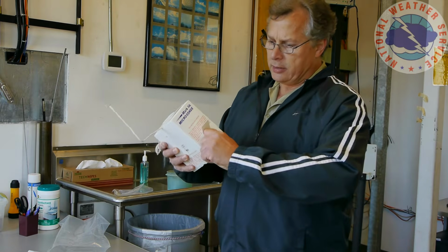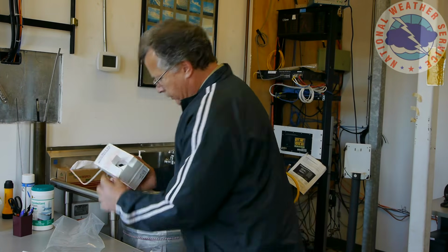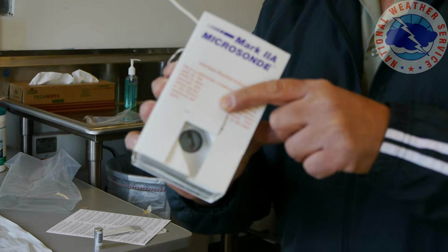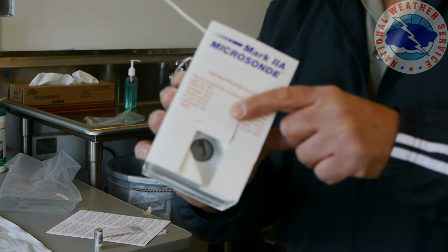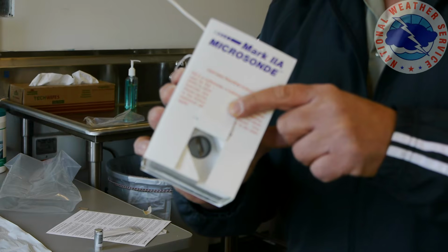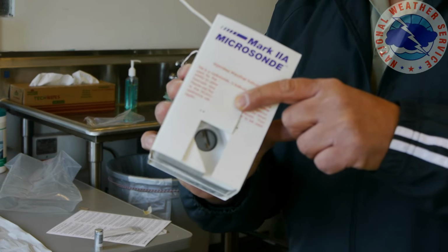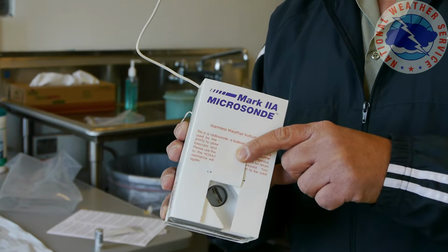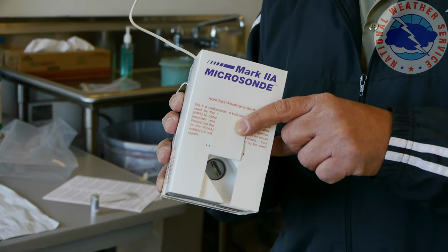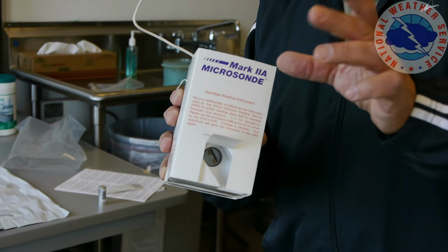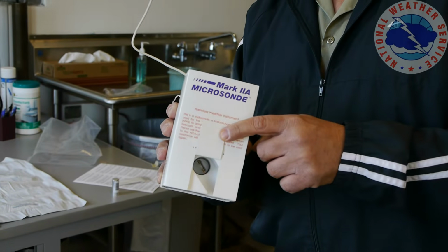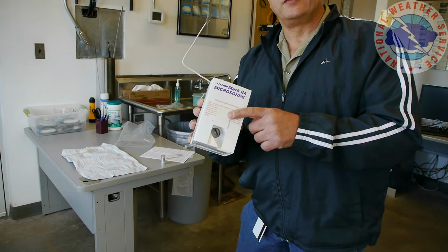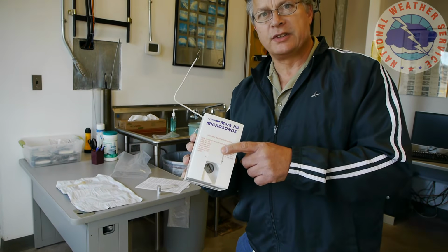Next is the measurement of the relative humidity, which is done by this device called a hygristor. It's a small piece of plastic that has rosin coated on it, similar to that used on a violin. Carbon particles are sprinkled on the rosin. That is then baked in place on the plastic. Rosin expands and contracts with changes in water vapor or humidity. That increases and decreases the distance between the carbon particles, which changes the electrical resistance, which is how it determines the relative humidity, based on that change in electrical resistance.